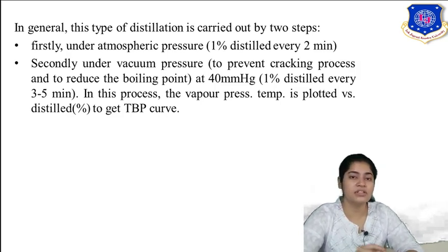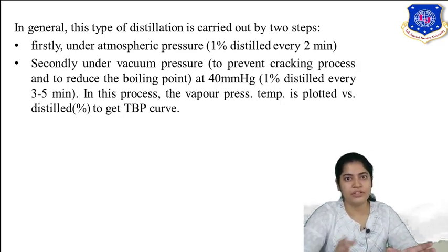For thermally sensitive materials, they are prone to cracking. What happens is nothing but a thermal degradation. Your original molecule will crack into other fractions. Now we don't want that. So what we are doing is, we are trying to decrease the boiling point.